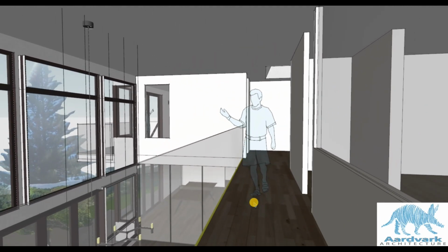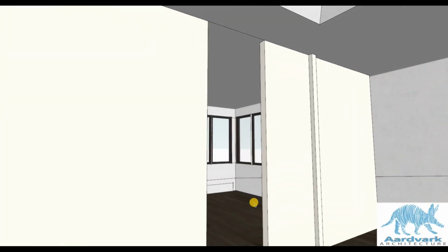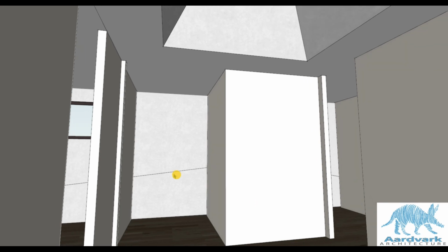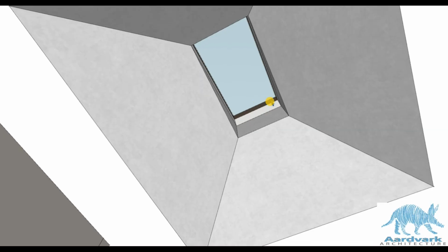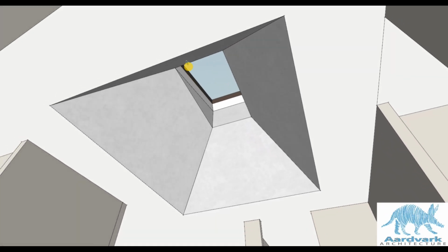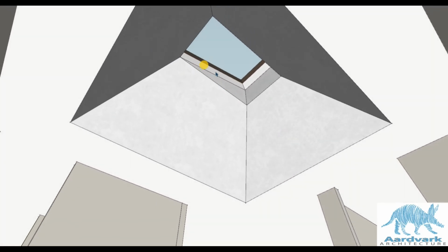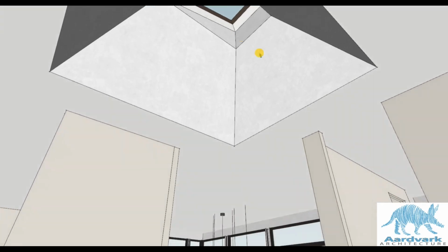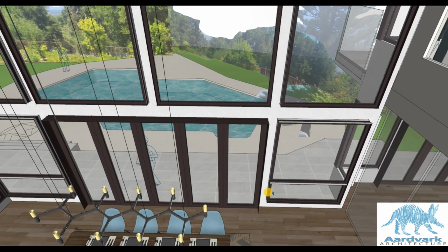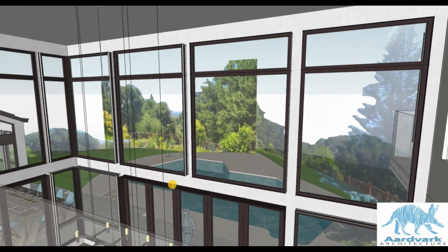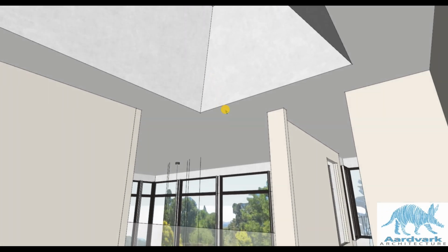This is amazing, right? Walking along this mezzanine towards this bedroom or towards that bedroom in the corner there, and the laundry alcove here, access to the bathroom, vaulted ceiling here, or I should say a flared skylight shaft here happening at this vestibule. And this would be an operable skylight. So you can crank this open to get a lot of really great stacked ventilation coming in through these operable windows down low, coming up and out through this operable skylight up here. That's going to be fantastic.